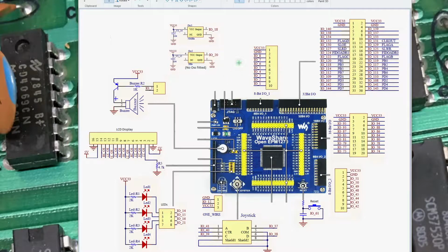We talked a little bit about that power supply where the 5 volts comes in off the USB connector. You've got that on-off switch we saw in the schematic. You've got the 3.3 volt regulator. You've got that poly switch sitting down here. So if you manage to short the 3.3 volt rail here, that poly switch will keep you from destroying the regulator. Of course, a power LED to tell you the board's on or off. This is going to be an input filter capacitor for the voltage regulator. I think there's a couple more capacitors sitting here.